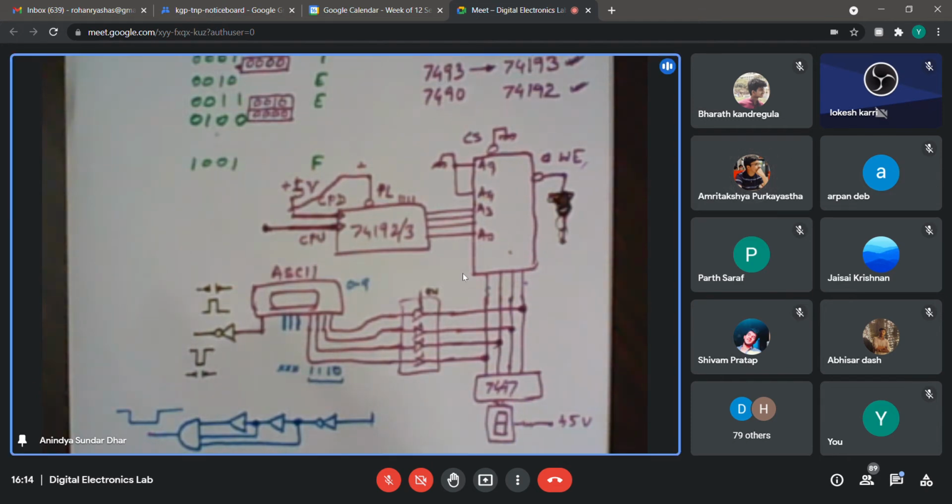You are doing that in the strobe signal, but what will happen, suppose I press some other character, at that time we don't want that to go into the write mode once again. Suppose P, Q, R, S, whatever I am saying, if you press any of those, I do not want to write, I just want to get into the display mode. So at that time the strobe signal should not reach the write enable or this enable. So that is the idea: if I press any key other than 0 to 9, then this should not be write enabled. So that is just interpreted as a command.